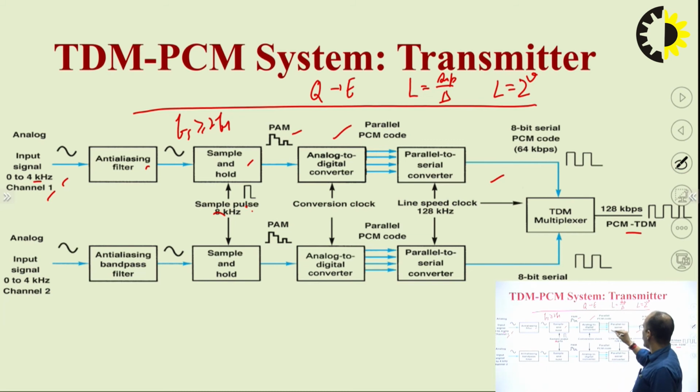So at this point let us consider this sample. For this sample we are taking 4 bits and we are getting the 1011 code. Here you have to understand one point very clearly. For a single sample, this system is creating data in parallel, meaning as soon as one sample comes into the picture, after the conversion we will get a parallel code of 1011.